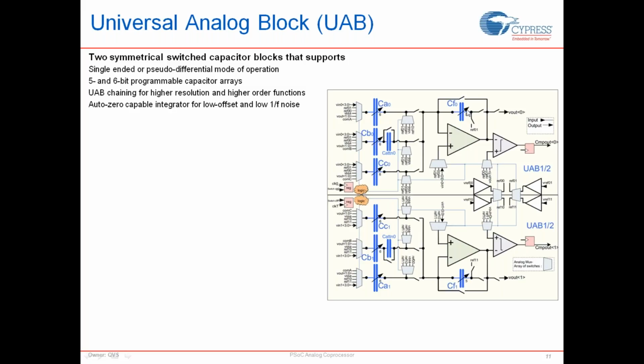That is, in a way, like your programmable gain amplifier or an amplifier circuit, where you're quantizing your charge going into the input capacitor, which is equivalent to an input resistance, and you're also quantizing the charge that goes through your feedback capacitor, which is like a feedback resistance. Effectively, what you've done is you've set up an amplifier circuit. So you could use these blocks to set up amplifiers. It's just one of the simplest things you can do with this.